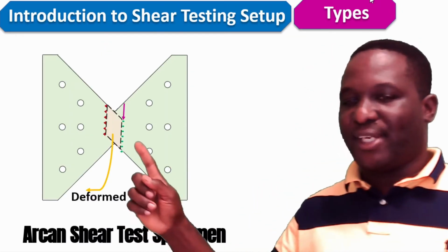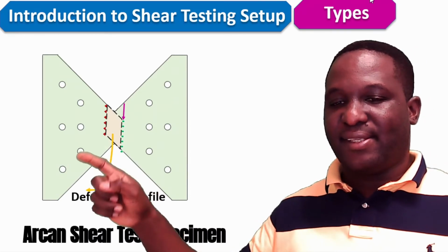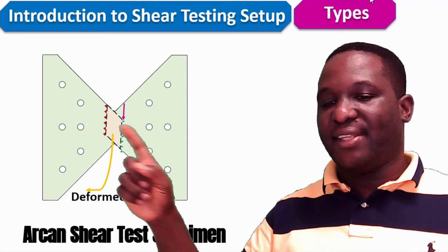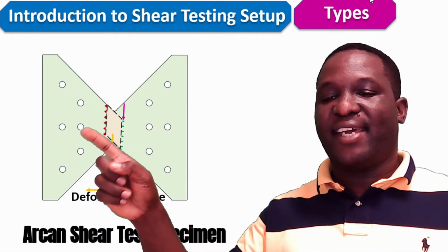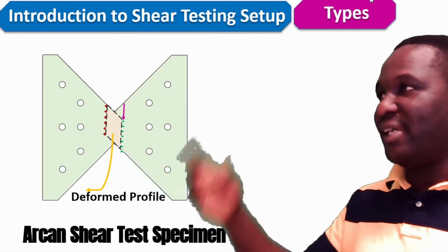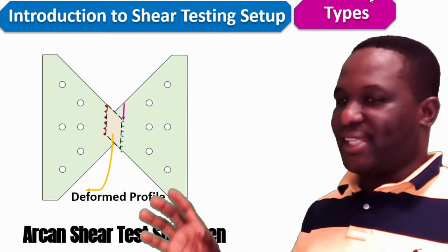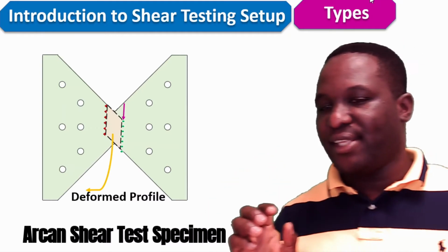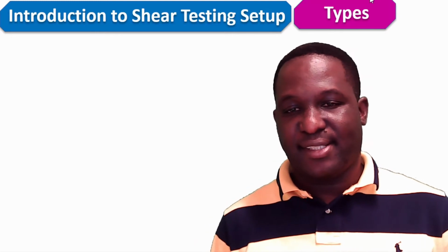Again, you would expect there to be a deformed profile. The left hand side of this specimen will have to be anchored securely, and the right hand side will have to deform, so that the back end becomes the fixed end and the front end, or the right end, becomes the part that is in motion. This is what we want to do when we're interested in shear testing for an Arcan shear specimen. We're going to be using this in demonstrating numerical insight associated with our shear test setup.